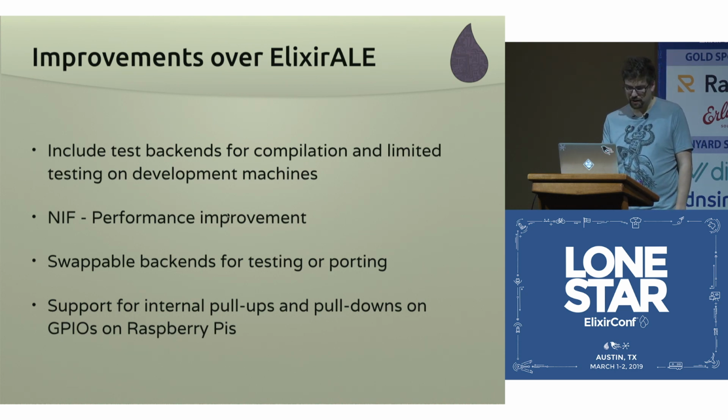And it also uses NIFs to get better performance. And as I was saying, you can swap those backends out to do better testing or for porting. And it's got support for internal pull-ups and pull-downs. The ElixirALE version didn't have that. So the built-in pull-up and pull-down resistors, it's got those supported too.